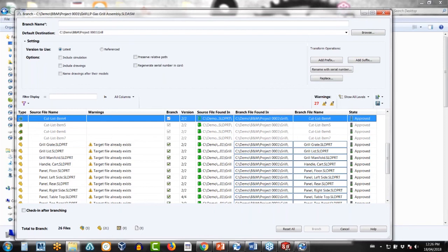Yeah, so if you're also using a vault where you disallow duplicate file name, then you have to give a different name, and that's why you have those transform operations. Use either a serial number or a different prefix, like design 1, design 2, design 3, that will mass change the name of the files here. The same thing with copy tree. When you use copy tree, you're basically creating new files as well, right? You're just not maintaining any references to its original. But if you're in a disallow duplicate file name vault, you would still have to use those operations here.